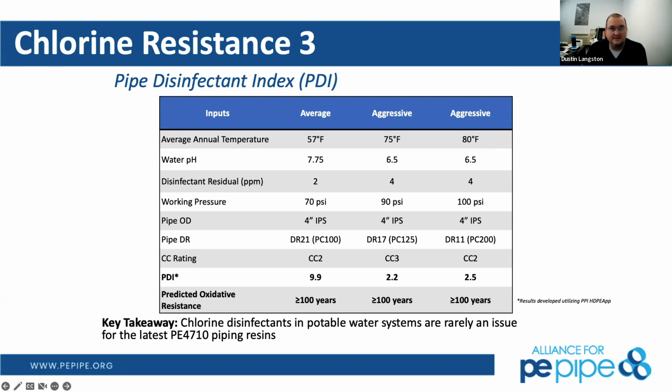Anything outside of the tubing sizes, chlorine's really not been an issue in the past. Very, very rare failures on the larger pipe sizes, just because you do have that wall thickness to support the pipe and pressure. But that's kind of the history of where we were seeing the failures, and where some of those rumors about polyethylene not handling chlorine came from.